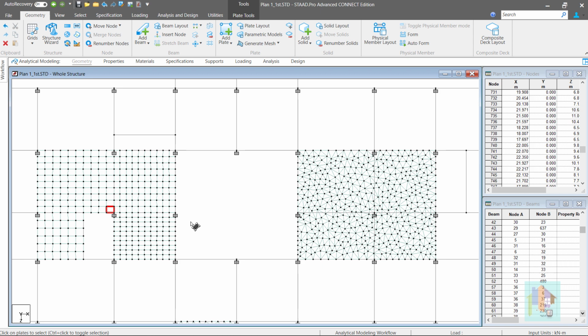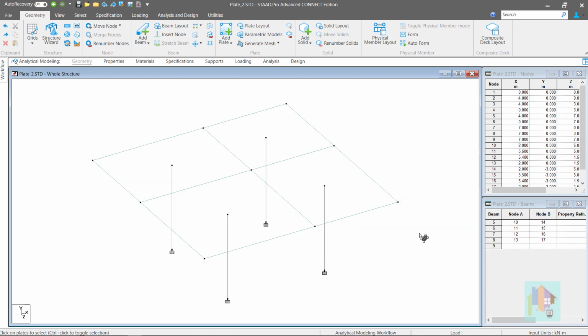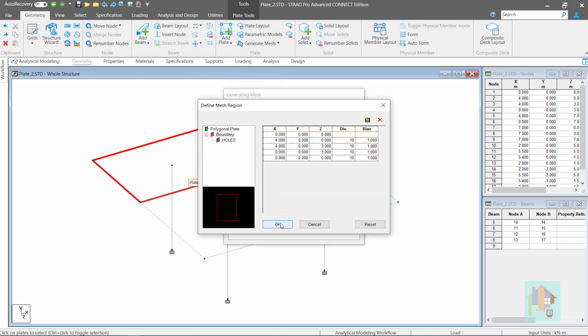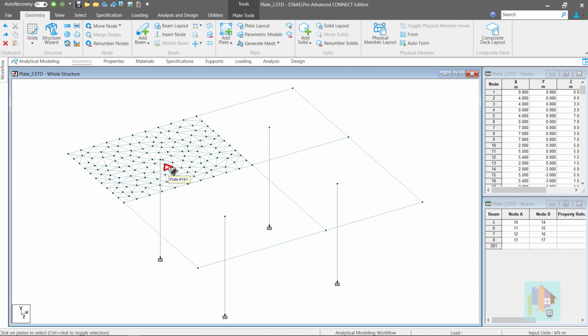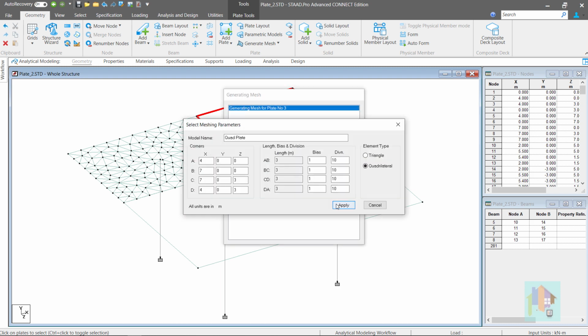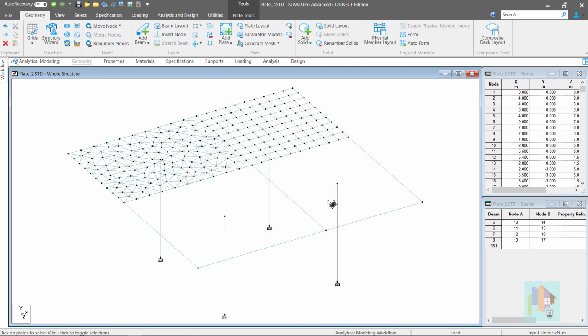and kind of boring. Same problem occurs if there is any internal node. Consider a flat slab or mat foundation where the column is connected to the slab without any beam. During meshing, this slab column junction node will not be considered, which results in improper connection. Also, this approach is unable to identify the existing boundary nodes, like nodes which are generated from an adjacent mesh or nodes of shear wall mesh. That's why we have to manually adjust all the edge divisions.